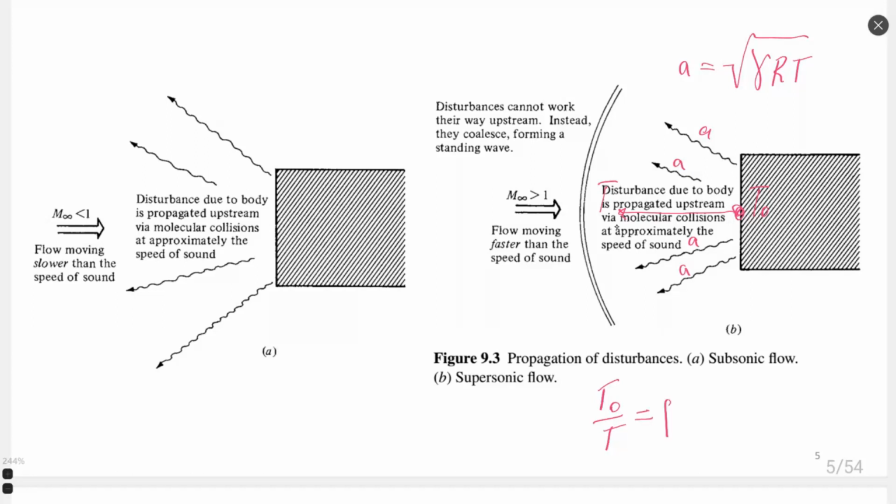It is always a function of Mach number. Since we assume that in all the region of the flow behind the shock wave the flow is isentropic, this analytical function works and describes perfectly the change of temperature with respect to change of Mach number. So we can know the temperature change.